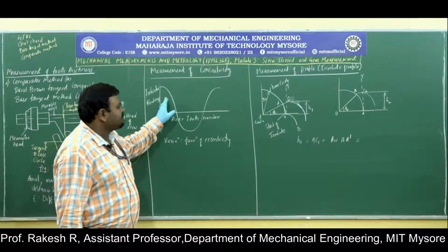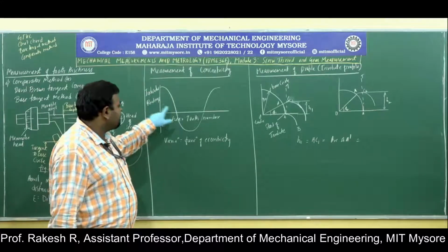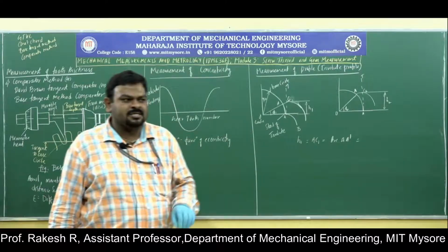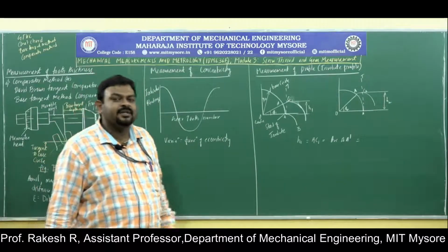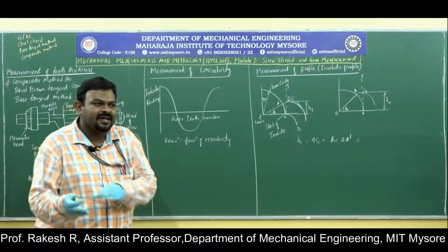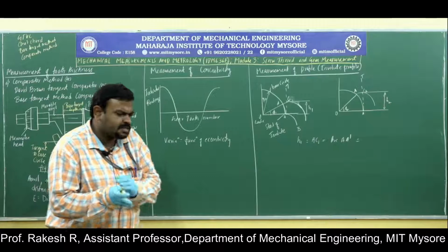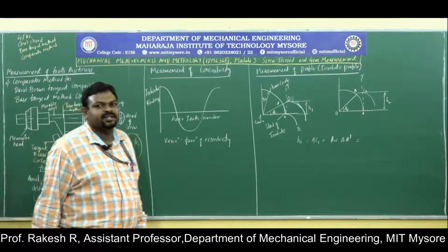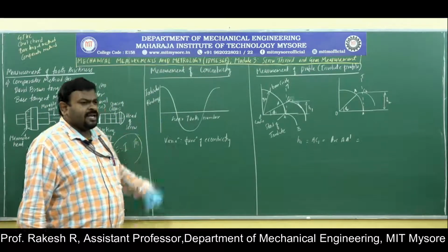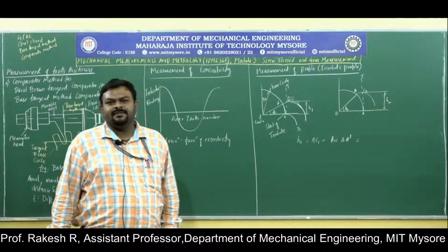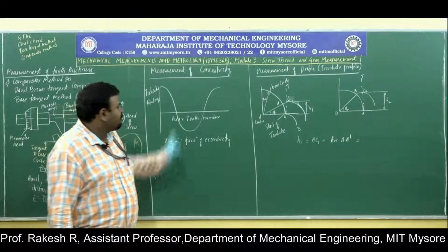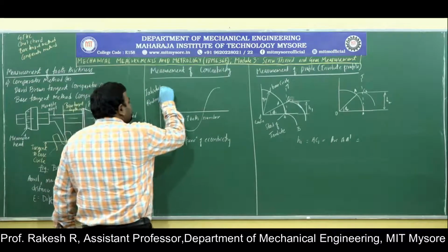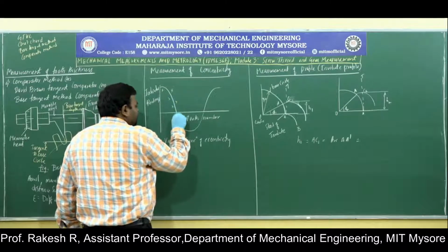Let us see, they have plotted a graph of indicator reading versus gear tooth number for different types of gear teeth. All the teeth must be concentric. If it is not concentric, then again there might be a power loss, again there will be a slip. Because of this slip, the gear may get wear and tear. Particular teeth will get damaged. And it is very difficult to achieve 100% concentricity. There is a limitation. We will be considering the gear tooth numbers as well as indicator readings. And if you just plot, the values will be nearer like this.